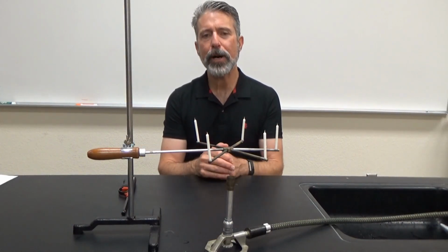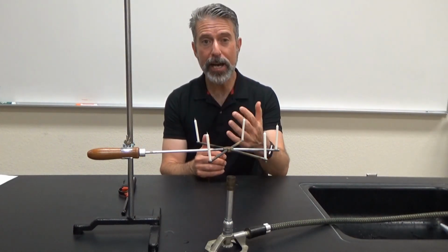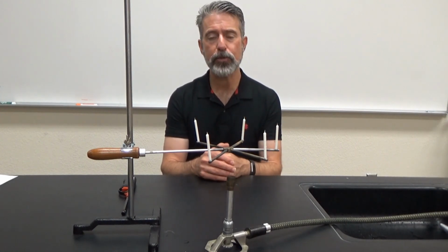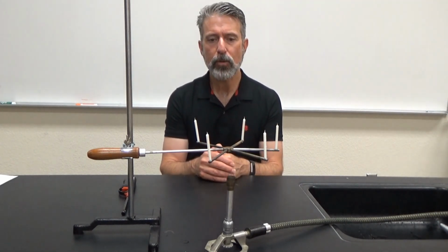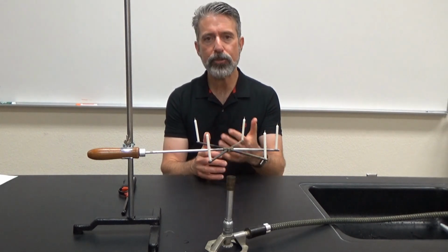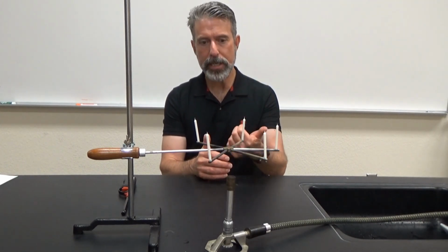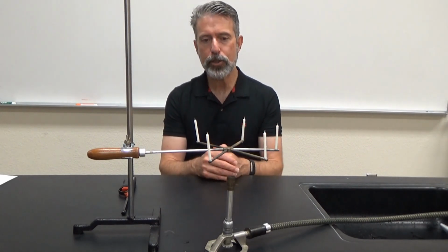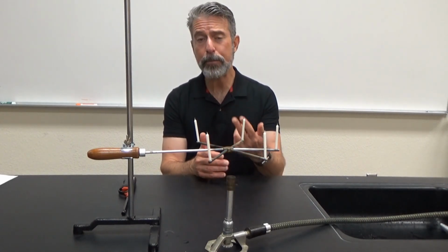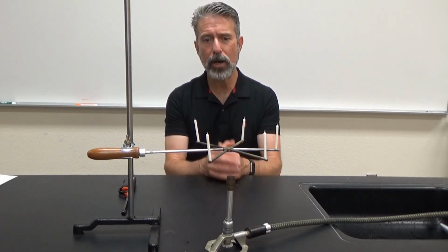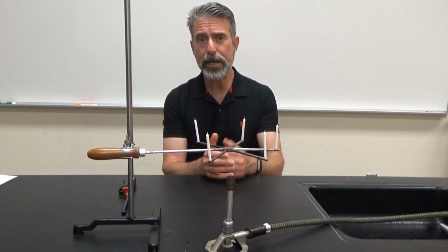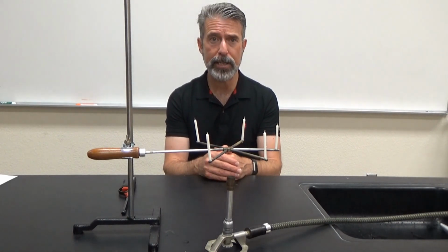So we've talked about factors that affect the rate of thermal energy transfer by conduction. We said that the rate of heat transfer via conduction depends upon the length of our slab, the cross-sectional area of our slab, the temperature gradient that exists across the slab, and it also depends on this property of the material that we call the thermal conductivity constant.